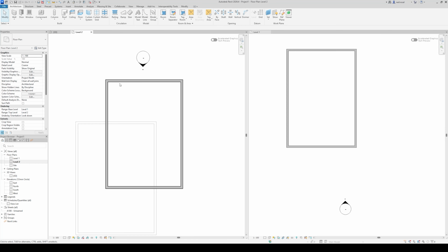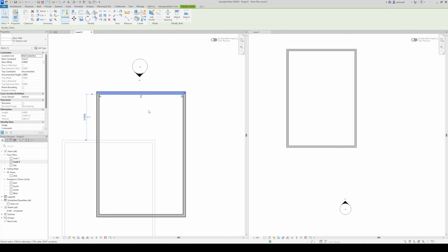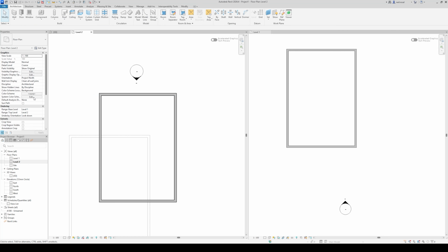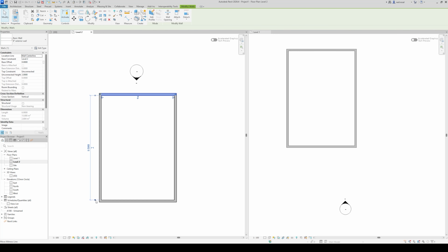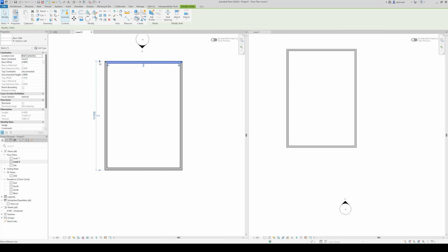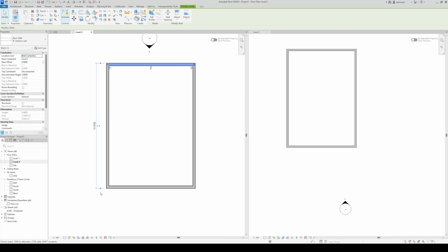I also forgot to mention that the measurements of your wall can be based on its center line, its exterior line, or its interior line. So you have to be careful of that when you want to be a stickler with your measurements. You'll see what I mean. So let's turn the underlay settings off for now. As you can see, it was referring to the center lines earlier on. In this case now, moving our witness lines, these small dots, it's referring to the exterior length.